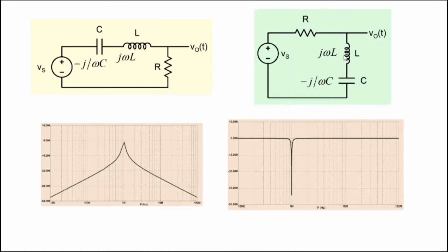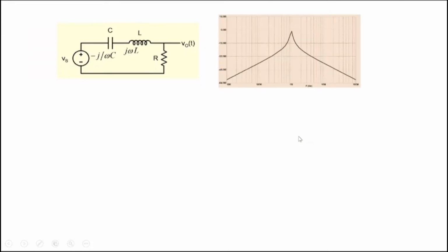And despite the best efforts, sometimes some little bit of AC voltage may remain in the circuit, in the power supply, and that AC signal can get into your circuit, and you're interested, of course, in removing it. So then what you could do is you could pass your signal through a band stop filter which is at 50 hertz, and thereby any 50 hertz signal that gets through is rejected, and everything else is then passed around.